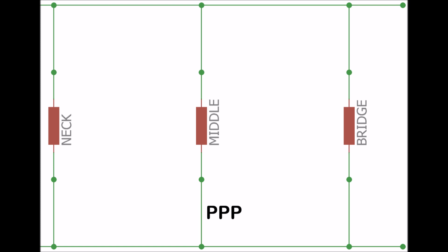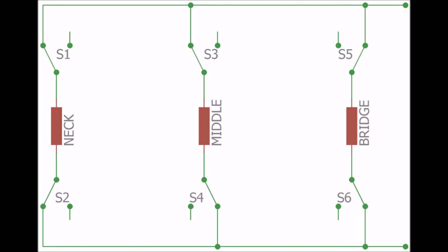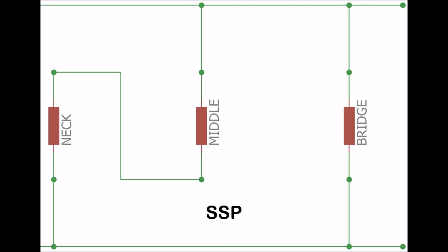The PPP combination is actually just connecting the pickups across the signal buses, and is by default, one of the 2 positions of the SPDT switches of each pickup lead. Thus, it may not be considered as part of the design process, inasmuch as it is necessarily inferred from its individual component connections, and vice versa. The SSP combination is only 2 pickups in series, with the other pickup connected independently across the signal buses. The SSP combination also solves the 2 pickup series combinations, as pointed out earlier.